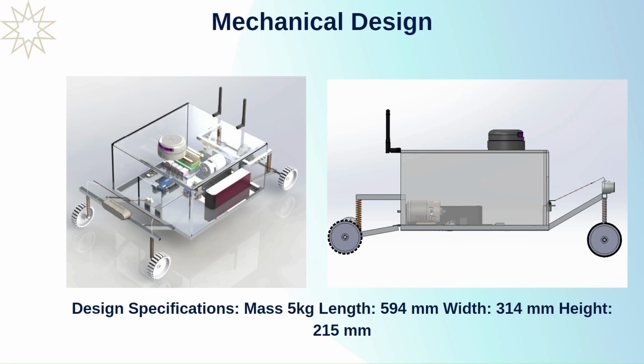The mechanical design of the project is as in the image. The front axle will be controlled with the help of a servo motor. The brushless DC motor will transfer its power to the rear axle with the help of a differential. The main structure of the chassis will consist of aluminum hollow bars. The rods will be connected with the necessary fasteners.